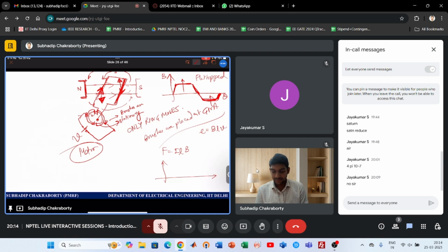EMF across this port. So this coil, when rotated in the other direction, will generate opposite polarity EMF. Now, if you connect some load with it, it will also see the opposite polarity EMF, which we don't want. We want DC, right? And if it is a motor, then we want the torque also to be smoothened. But assume that it is acting now as a generator.